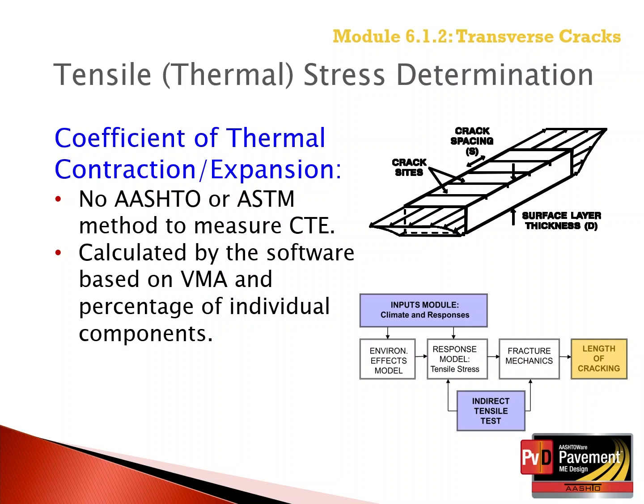However, some agencies have reduced the area of the transverse cracking transfer function by deriving the coefficient of thermal expansion contraction through local calibration for specific aggregates and or asphalt mixture types.